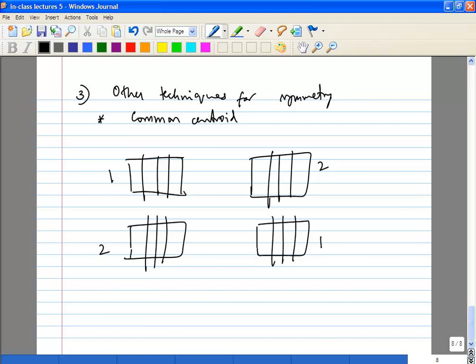It's quite common. Now the only thing you have to be very careful about is this is very layout intensive, because now let's say you had to connect out these gates. So now you have to route the gates, you have to route the source and drain connections. So it's actually very intensive. And I would say in RF layouts, it's only of limited value. But like I said, there's always an exception. You may find a case where you might want to use it.